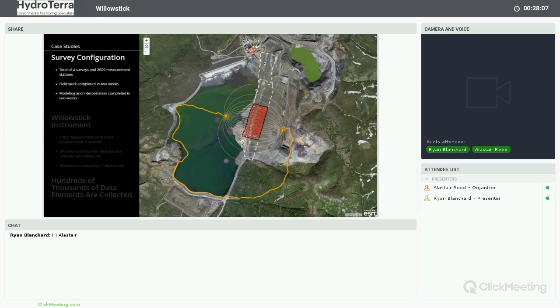So just to help orient you and give you a little context, for each project we have 2 electrodes. We place the down gradient electrode, in this case in the tailings storage facility, and then we place the up gradient electrode in the waste rock dump itself, and then we connect those via a 14 gauge copper wire. And then you see these white lines here. These represent the distribution of the electric current through the area of interest.